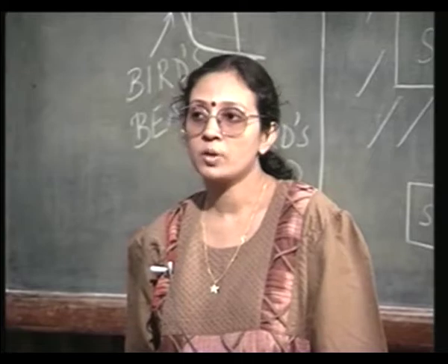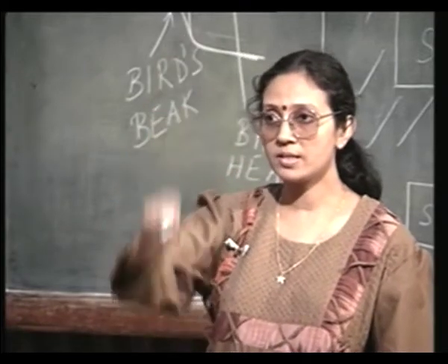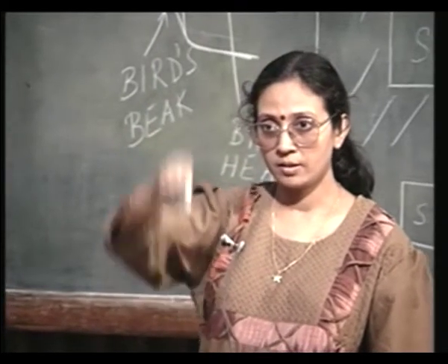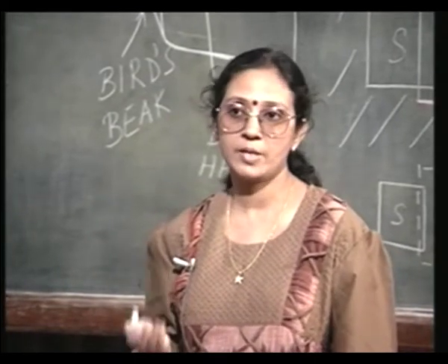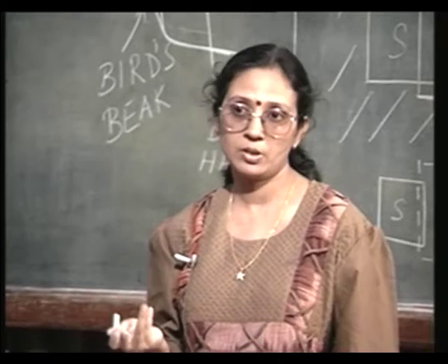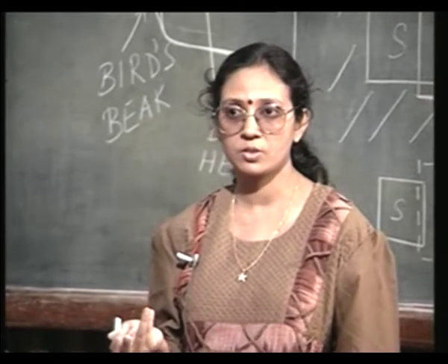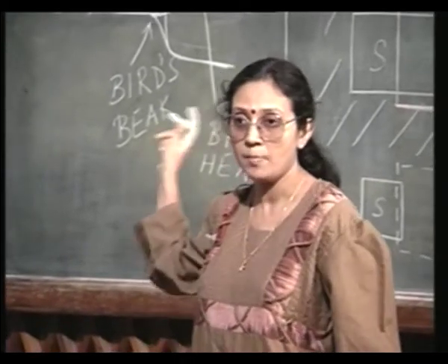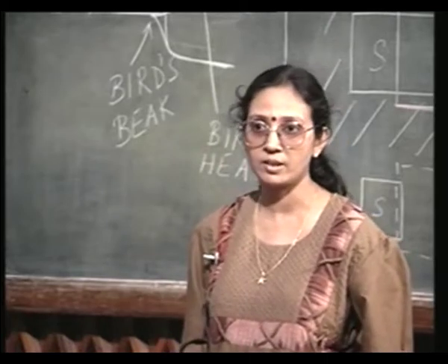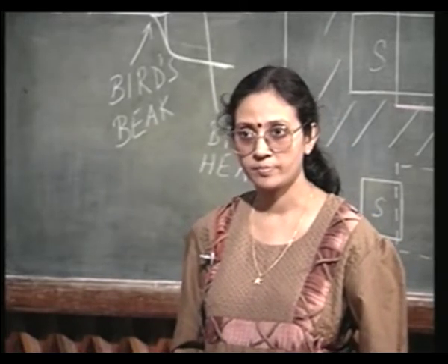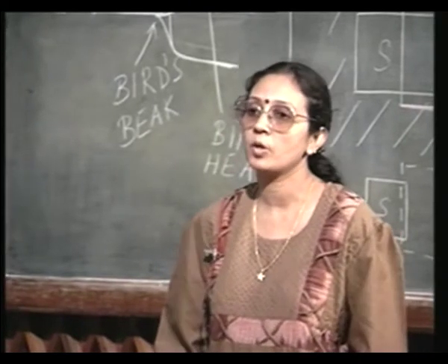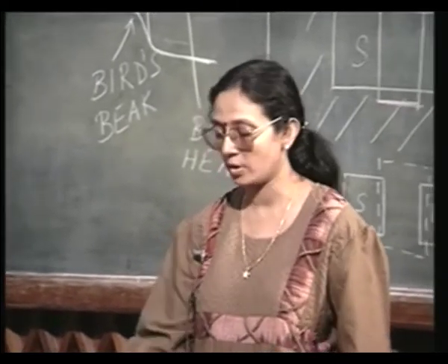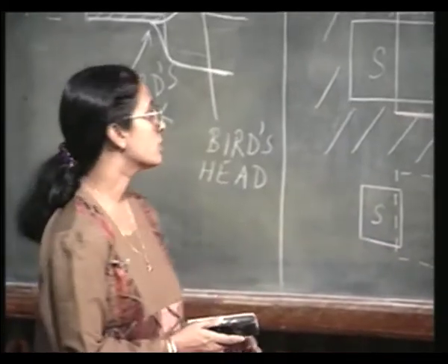Okay. In case of bipolar junction transistor, the device is actually vertical, it is a bulk device. So, nothing really gets affected, neither the base width gets affected, consequently the beta of the transistor does not get affected. But here if the channel length gets affected, that is a very serious problem. So, particularly for MOSFET technology, the bird's beak problem is a very serious problem, and one tries to prevent it by various ways.